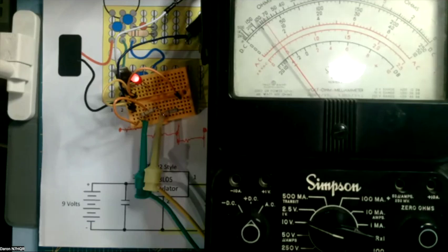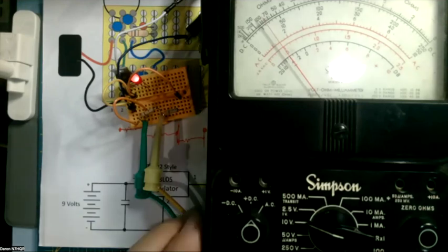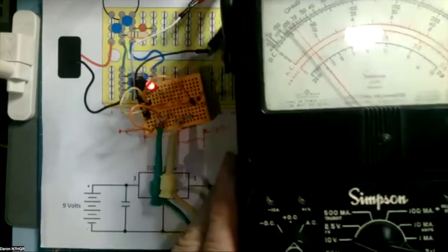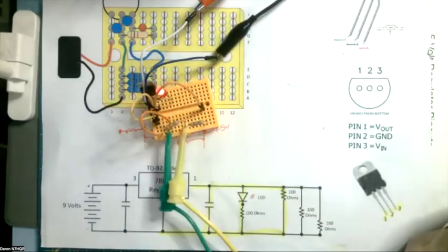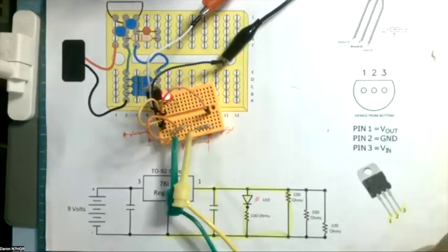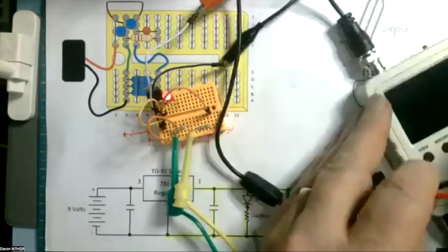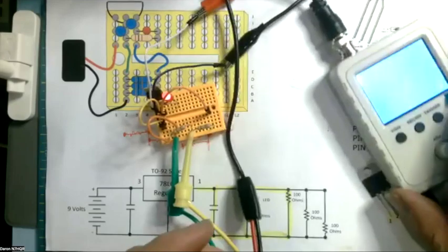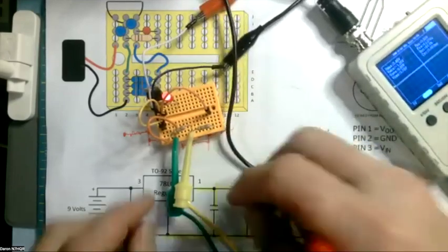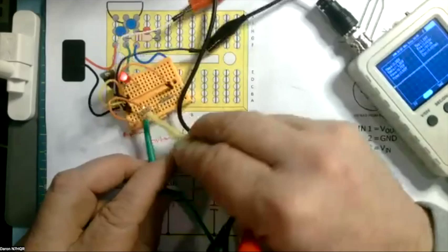So if you're using one of these old analog meters, you have to be very aware that it will very likely change the reading that you have if you're not reading something that's low impedance, like a power supply or something like that. Hence the difference between the VOM and a VTVM. A VTVM is a vacuum tube voltmeter, which had an input impedance of 10 million ohms.